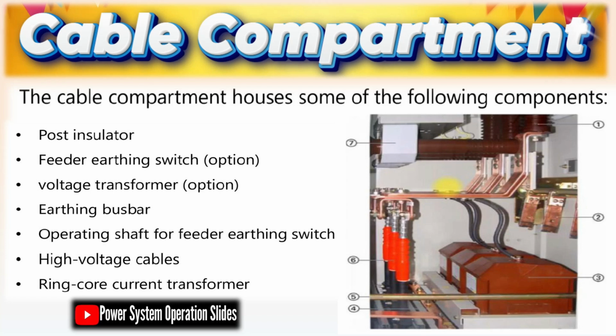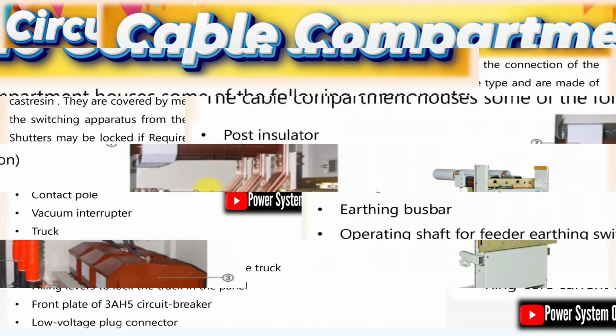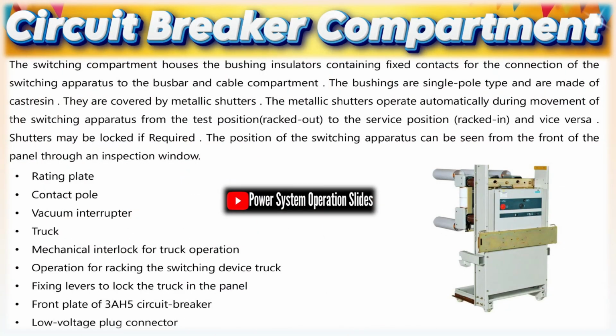Lockout relay, 86. Provides mandatory manual reset after severe faults, preventing automatic re-energization. Coordinates multiple tripping functions for critical equipment. Ensures safety in post-fault inspection.